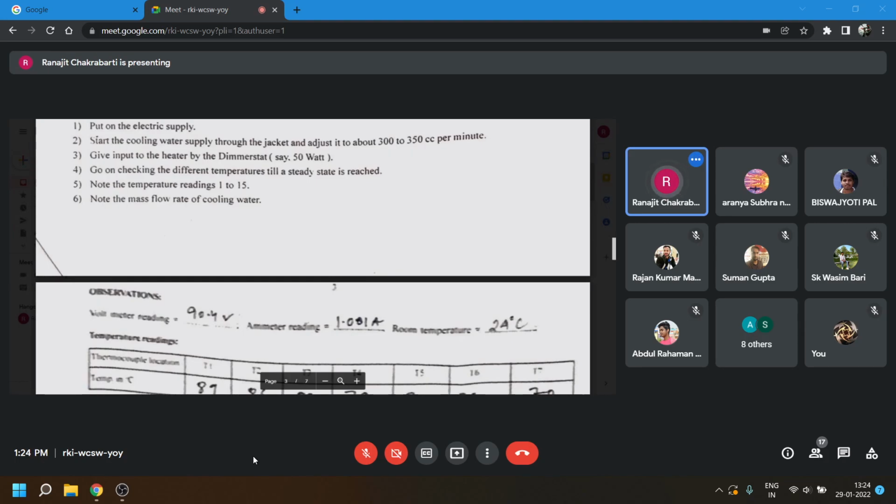If you have a rod which is heated at one end, cold at the other end, and through that rod electric current is flowing, then there is also a heat generation. If there is an exothermic reaction going on, or an endothermic reaction going on, then there is a heat generation or a heat loss. But that term is not coming here because here we have a rod made of metal, simply a rod of uniform cross-sectional area, which is heated only at one end.